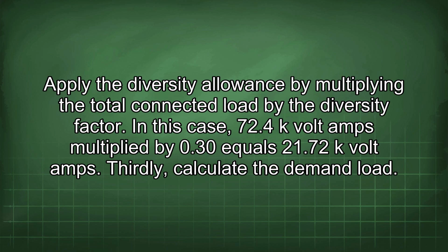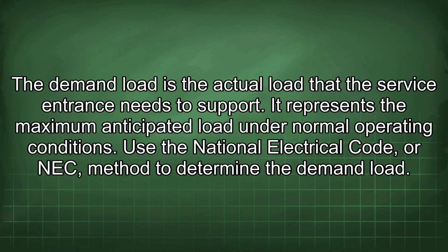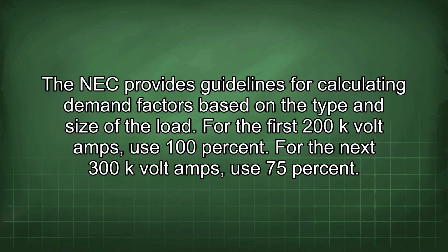Thirdly, calculate the demand load. The demand load is the actual load that the service entrance needs to support. It represents the maximum anticipated load under normal operating conditions. Use the National Electrical Code, or NEC, method to determine the demand load. The NEC provides guidelines for calculating demand factors based on the type and size of the load.